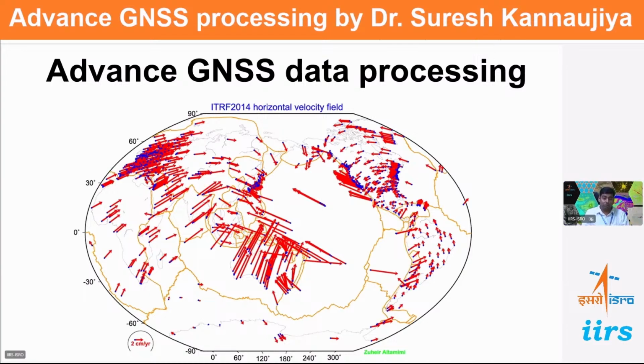then we can think of millimeter accuracy, because there are many important internal factors, like phase center variation in the antenna. If phase center variation is less than 1 millimeter in horizontal as well as vertical, then your capturing of these electromagnetic waves in a particular frequency like L1, L2, L5 will be accurate.